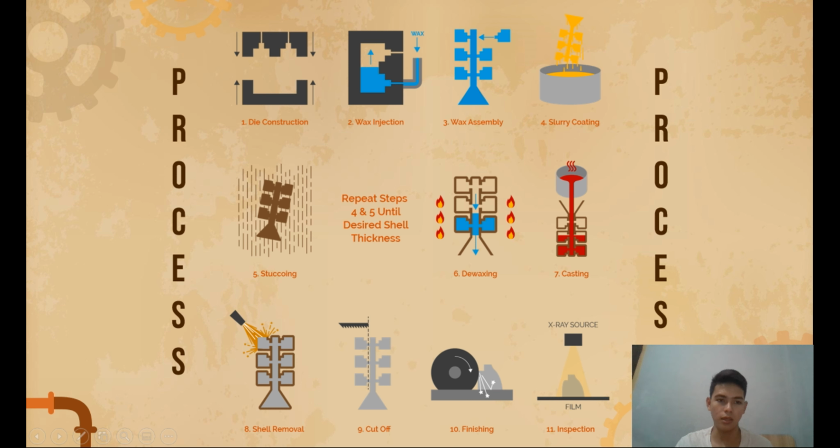And the last is testing. Once the finishing operations are done, the parts are inspected for surface and subsurface defects. Visual and fluorescent penetrant inspection is done for surface defects, and an X-ray is employed for subsurface defect identification.